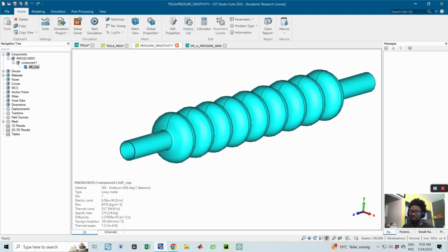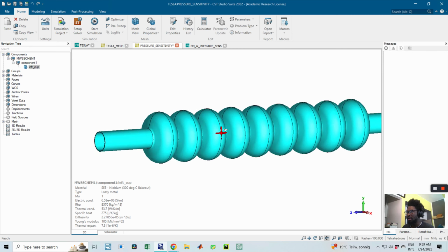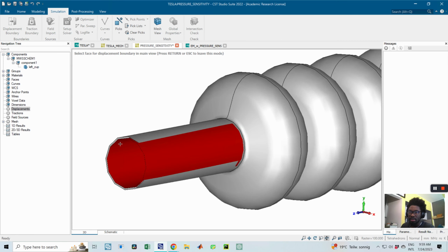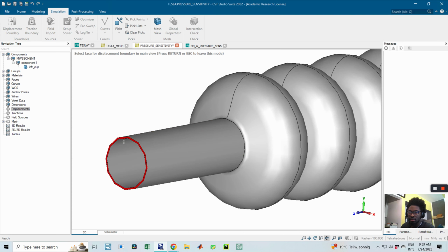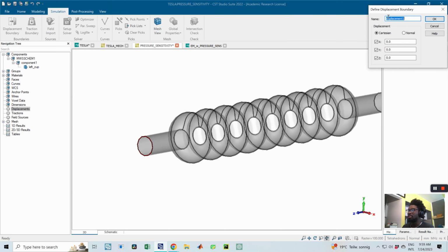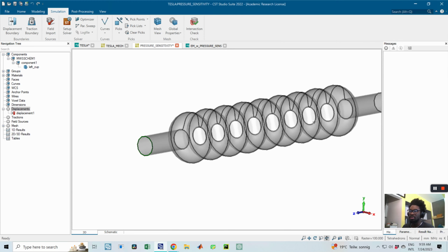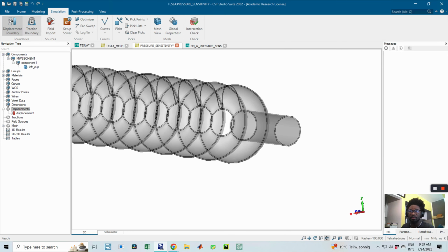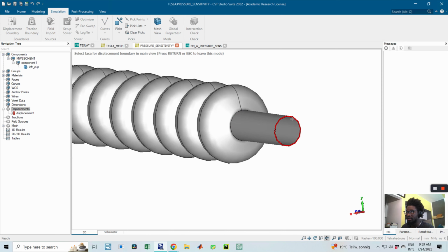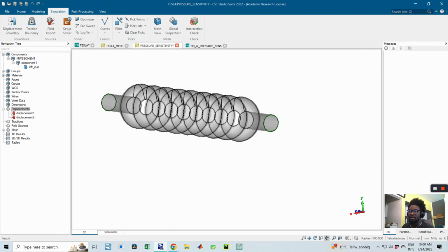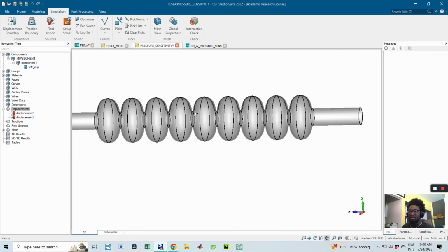I think this video will be short because it's not much different from what we did in the previous tutorial. So I'll just go ahead and apply my boundary conditions, which are the same as last time. Just to note, your results greatly depend on your boundary condition. I'm fixing this end and also fixing this other end. I'll do a video in the future that has varying stiffness at the boundary, so you can see how the deformation varies with the stiffness at the ends of the cavity.